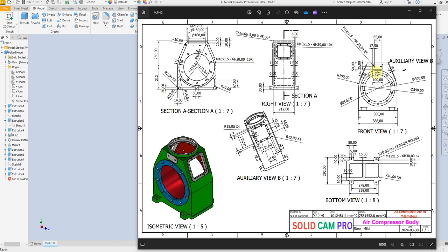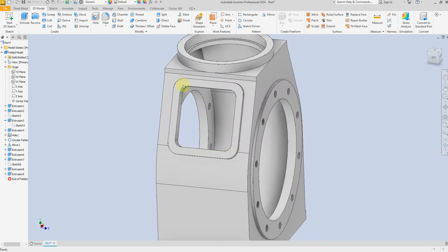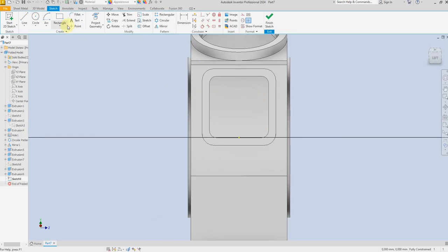You see here we have these two flanges, thickness 6 millimeter outside, and the same for this one. We have 6 millimeter. We have these two flanges here, 6 millimeter, and we have the dimensions here. So let's create a hole here, tapped hole, and select. Let's select project geometry and select this